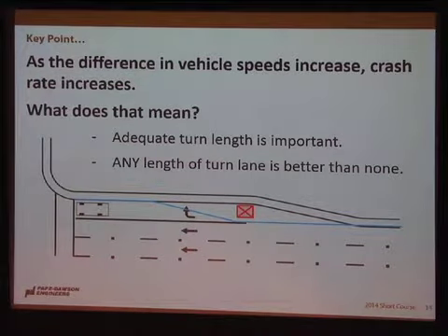So one of the things, of course, providing adequate turn lane length is very important for operations and safety. But one of the things that I always say is that any length of turn lane is better than no turn lane. So if you're forced into a situation where you can only provide a certain amount, then provide that amount and move forward.